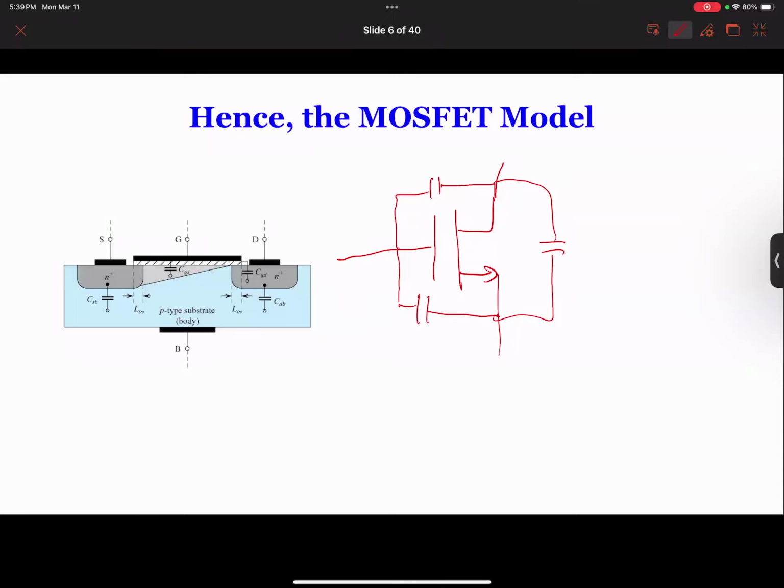So then you might say, why do you have 4 or 5 here, but only 2 here? The issue is that modern MOSFETs always have a body. And there's always a capacitance between drain and body, source and body, and gate and body. The gate and body can typically be neglected, but the drain to body and source to body cannot be neglected.